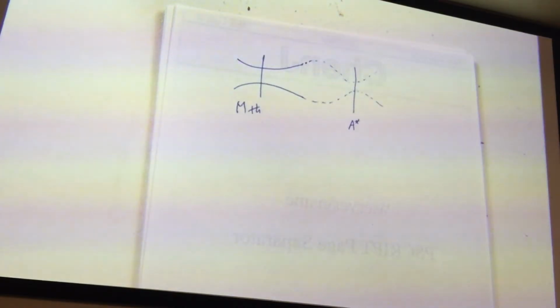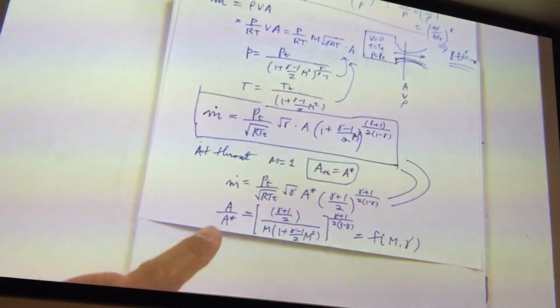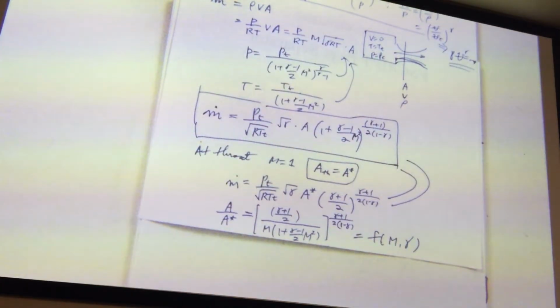So, the other interesting thing about this is your area ratio determines your Mach number for a given gas. So, within the context of isentropic flows, it does not matter whether you have a big gun or a small gun. Right? You can have a huge rocket or you can have a small rocket. As long as the area ratio is the same, you will produce the same number. Make sense to you? I don't know whether you were able to play with some model rockets, small rockets.